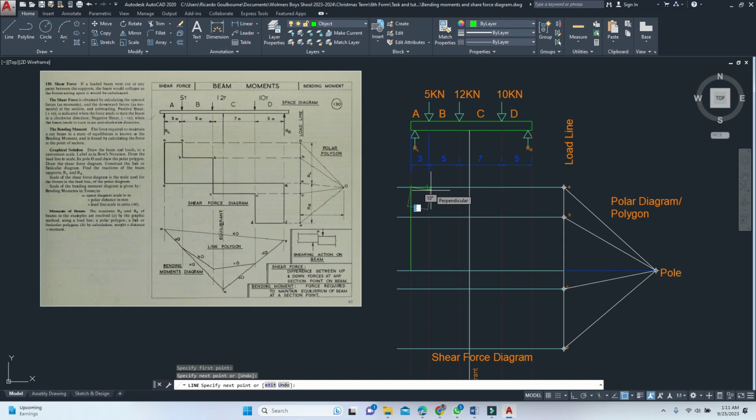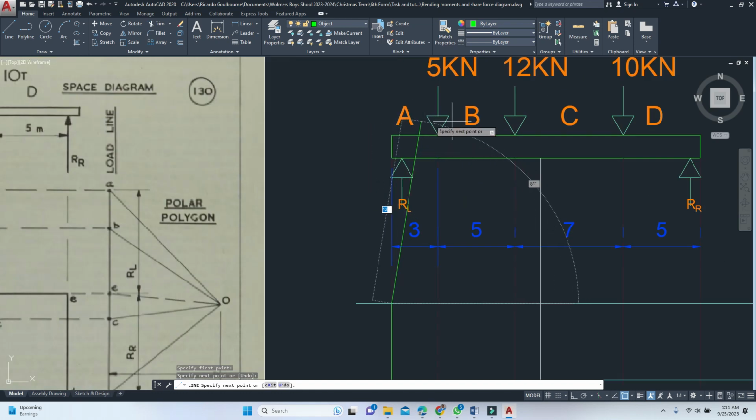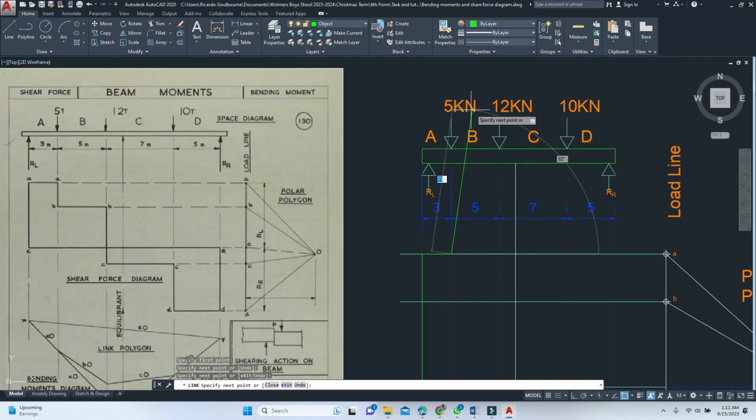So here's what happens. Here is all nice and dandy, everything is running smoothly, and it's all nice and smooth until it gets to the 3-meter marker, which is right here where this 5 kilonewton force is happening. You can imagine this as you walking with your hands out, and then somebody throws a bag of cement in your hand. What is going to happen? You probably stumble a bit, your hand is going to sink. So this is what is happening here. A 5 kilonewton force drops on it, you simply dip, and it dips to the next force level.